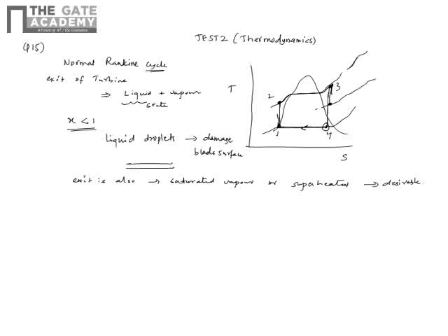It is expanded to some state, and then it is again heated, and then expanded again in another low pressure turbine. So you have two stages of turbine, and in between you have reheating. You supply heat, and then you expand in the low pressure turbine, and this is where the output is. Now at the exit of the turbine the state of the water will be superheated, so you avoid this damage to the blade surface and so on.